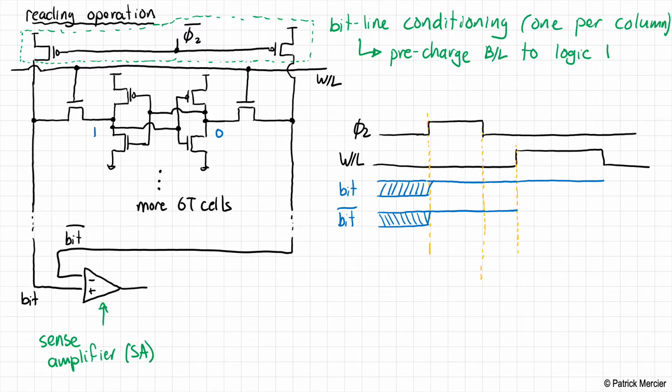Even though these SRAM transistors are tiny, the smallest possible transistors that you can design, simply because we prefer to design for density in an SRAM rather than performance. These are the smallest transistors you can possibly lay out. But that one NMOS transistor in the right inverter that's tying its output to logic 0 is statically on, whereas the word line is just dynamically floating there.